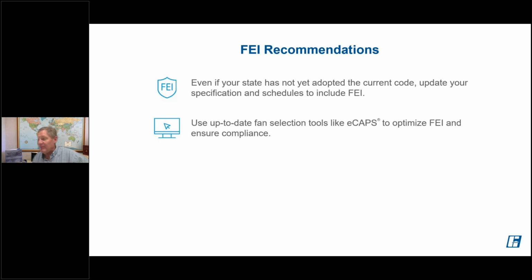Make sure you're using up-to-date fan selection tools like ECAPs. Most manufacturers now have already updated their literature and their software to include FEI. Again, that was largely driven by the fact that anybody that wants to do business in California had to have their FEI stuff in place by the 1st of May. So that's probably done for most manufacturers now.